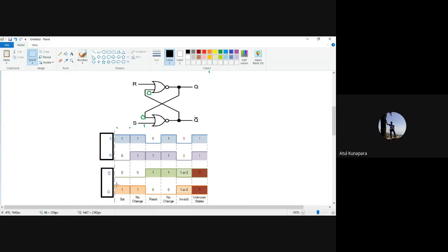Okay, prior to this timing frame, let's say your S is equal to 1, and let us see your output here, it is 0 and 1. Initially it is here 0 and here it is 1. So what will it be doing? When you are giving set input equal to 1, logic 1, and reset equal to 0, for this time it is giving you output logic high at Q, and Q bar is made 0.